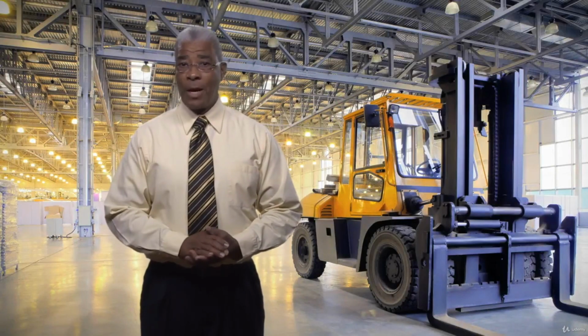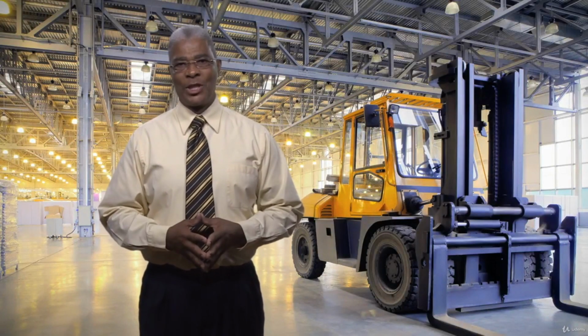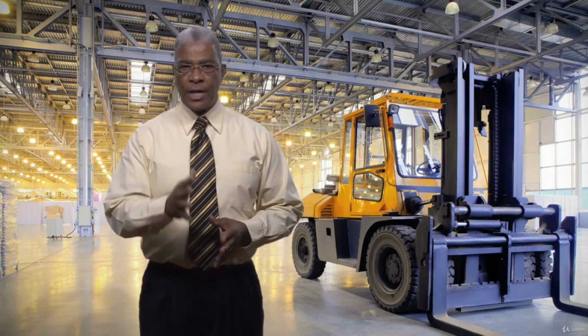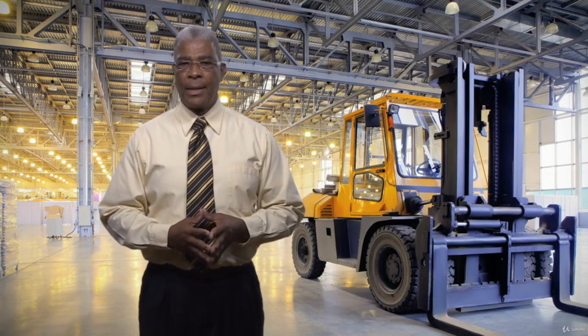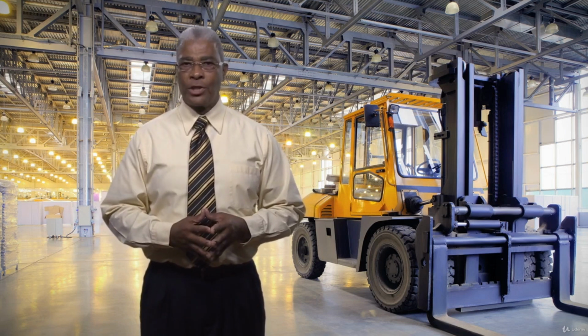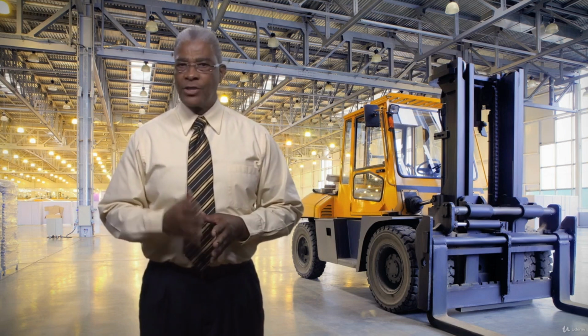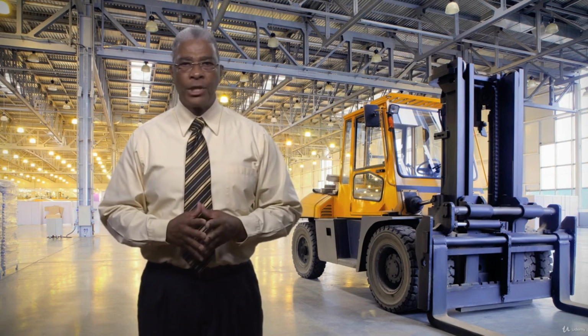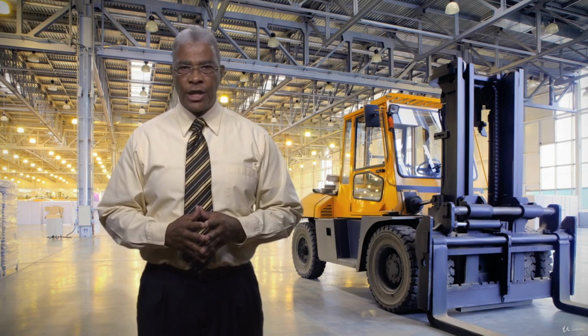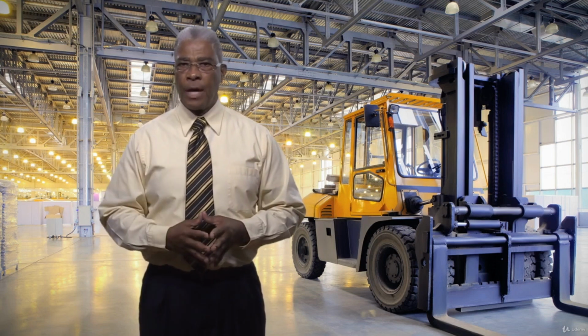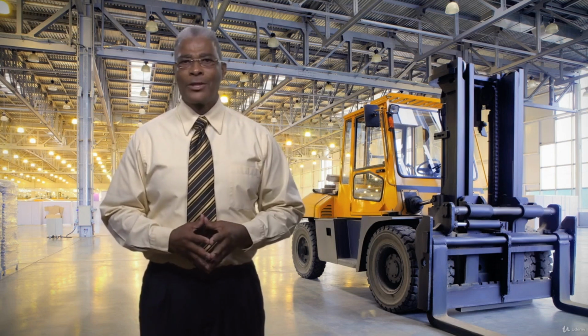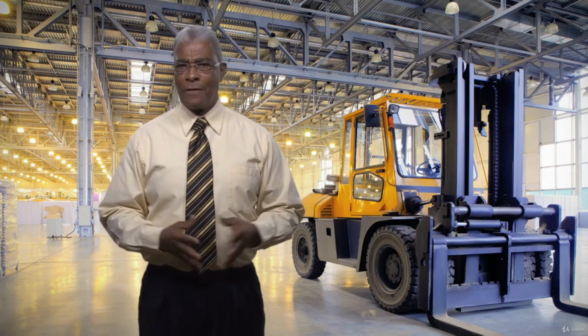Each department must be responsible for the implementation of lockout-tagout procedures. Employees must have training and understand the significance of implementing the procedures. Employees must use the lockout-tagout procedures when working on or near de-energized circuit parts or on equipment where there is a danger of injury because of unexpected energization of the circuit parts or unexpected startup of the equipment. Training must be provided so employees understand the purpose and function of the procedure.